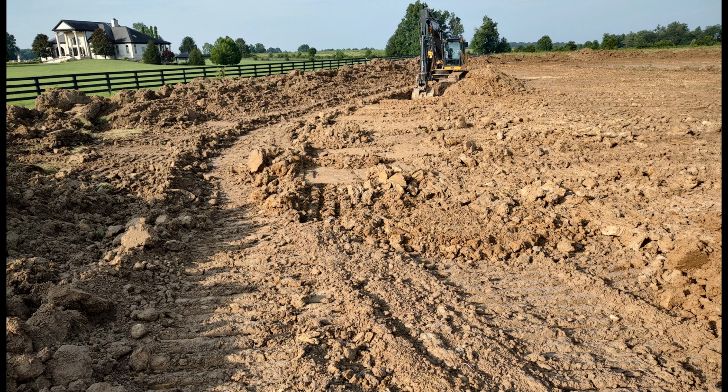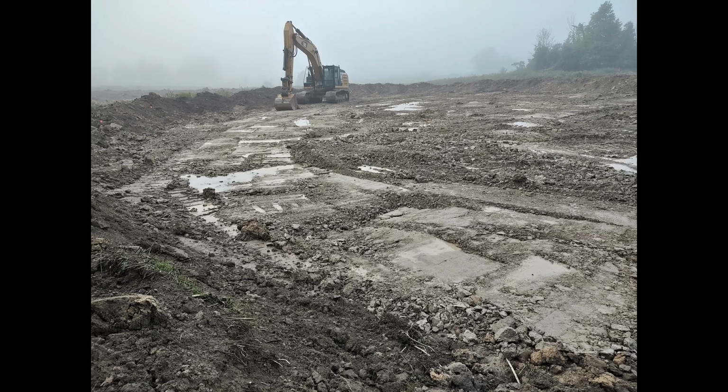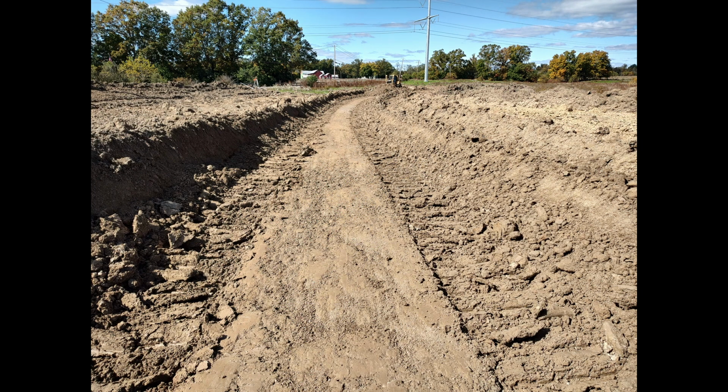An open trench should not be left for any length of time, or it could be a hazard to both humans and animals. Another problem is that the open trench may fill with water or cave in. The excavator is completing the construction of a groundwater dam. The soil was placed in the core trench and compacted in layers using the excavator's bucket and tracks. The windrows of soil you see on the left are primarily topsoil that will be spread over the groundwater dam and in the wetland basin.